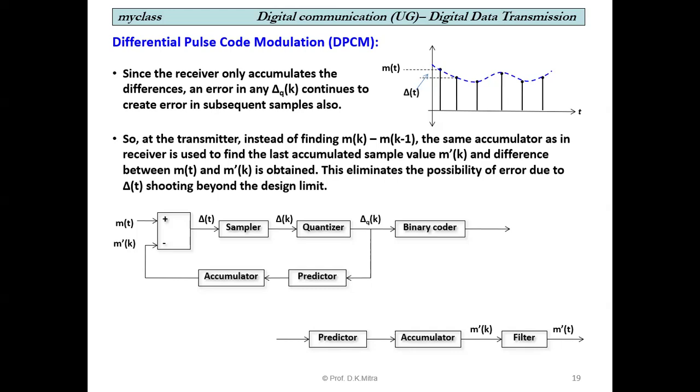In electronics systems, there are many such applications of predictor circuits, which predict the possible value. Because if you are taking sample values of human voice, and if you are tracking or sampling the voice for the last 5 minutes, maybe 5 million samples you have taken, then it is always possible for a predictor to predict what should be the next value, with some, of course, plus minus error. On the receiver side, there is a predictor and there is an accumulator, another circuit.